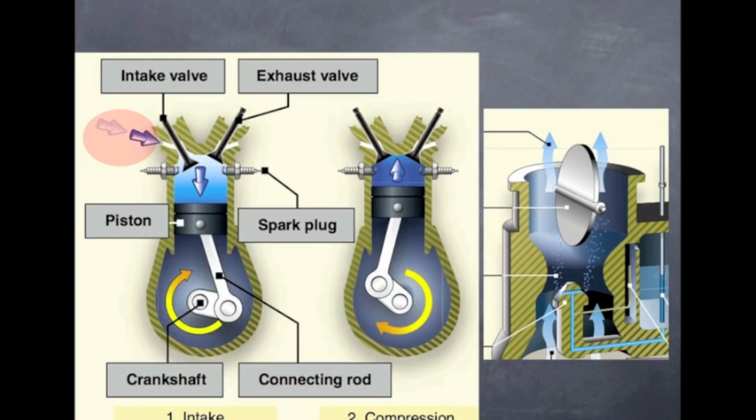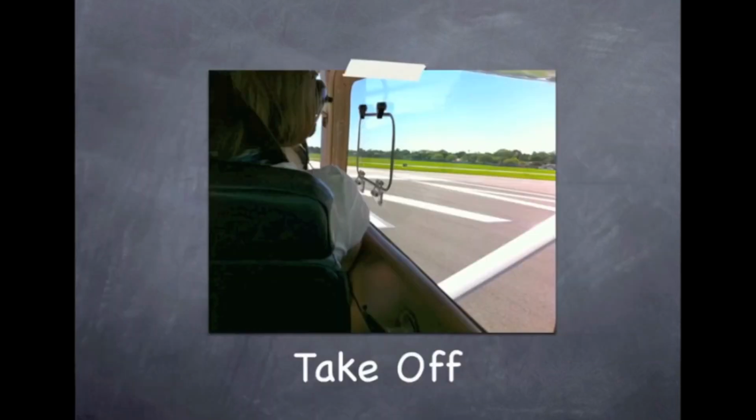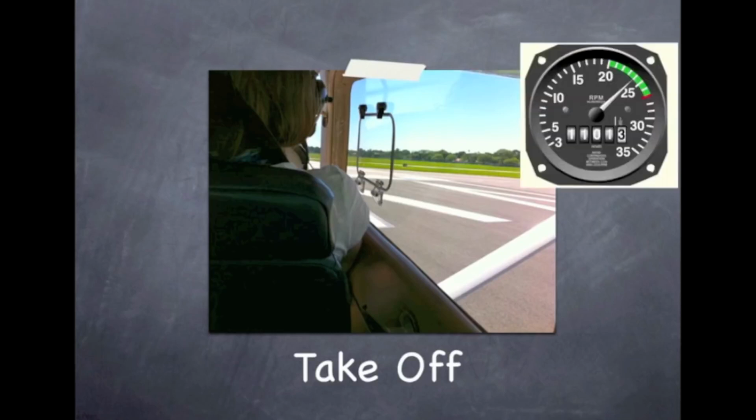We'll look at this again later when we decide to set our cruise power in flight. But let's first take a look at our takeoff configurations. During takeoff, we need most of our power converted into thrust. Remember, we're not moving through the air very fast, and the low pitch angle does a few things. First, it keeps the angle of attack small and efficient with respect to the relative wind.